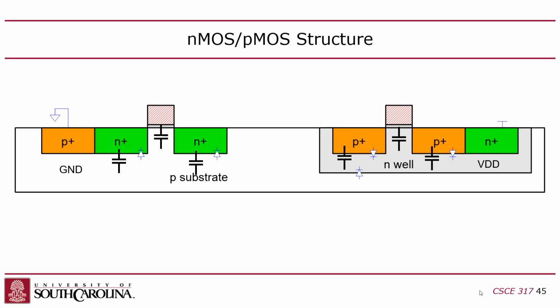A reverse bias diode is essentially that, because the dielectric becomes the junction in the diode where the charge carriers are repelled from one another, right? So you have a diode. In a diode, when you try to reverse bias it, the junction partially becomes kind of an insulator, and you end up with a capacitor.